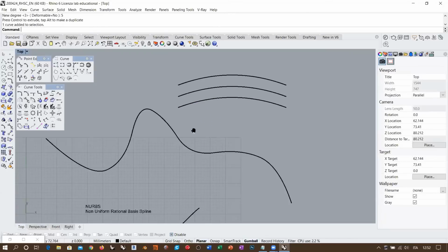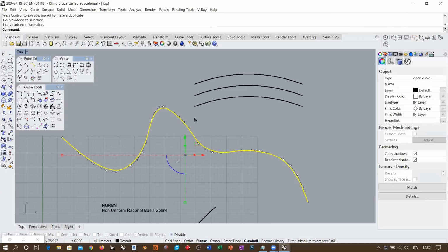So if I want to change the shape of a curve more smoothly, I don't increase the degree, okay? I decrease the degree. Because if I decrease the degree, what happens is that one control point will affect a larger portion of the curve. So if I increase the degree, I don't change the shape, which is something that, from an intuitive point of view, is what any designer would do. I want to increase complexity without changing the shape of the curve.